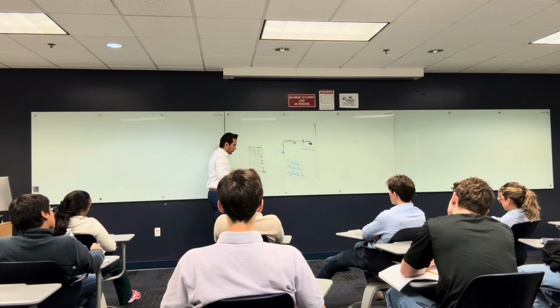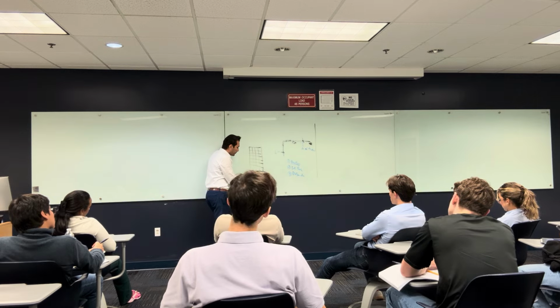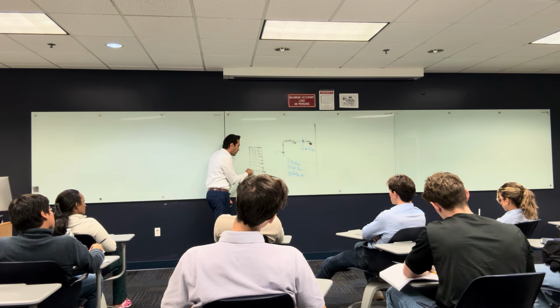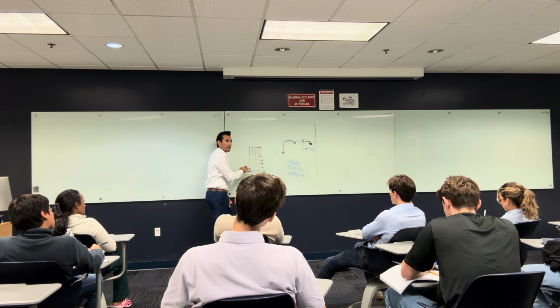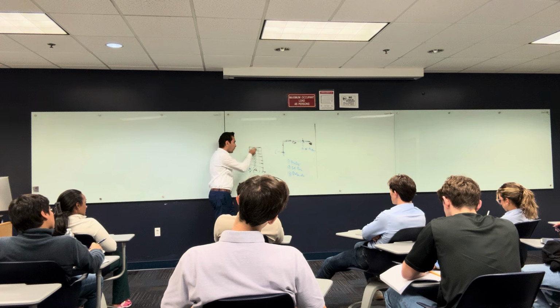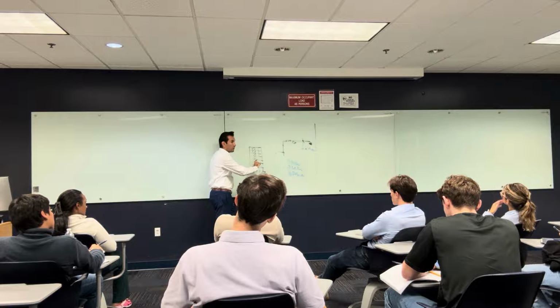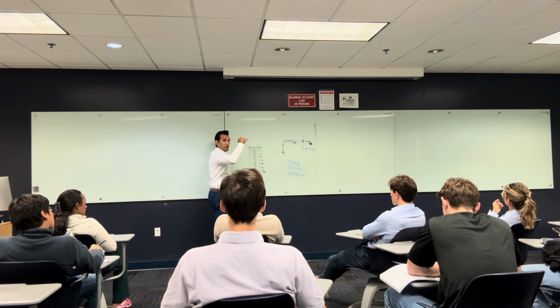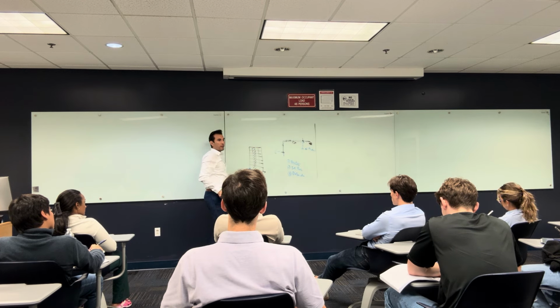we want to know the reactions at the columns, and we want to know the normal force, the shear, the bending moment, everything at each one of these columns, so I can design the columns. If you have a shear wall like this, you want to know the forces at the base, and not only the base but at many sections. The way we design shear walls in a tall building, you can make one section each 5 stories. You take the 5th story, get the normal forces, the shear and the moment, design it, and replicate this in the next 5 stories.